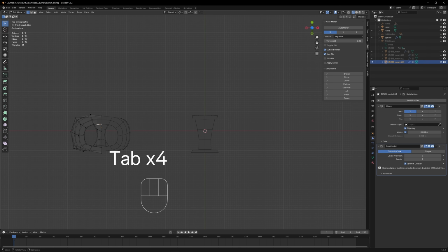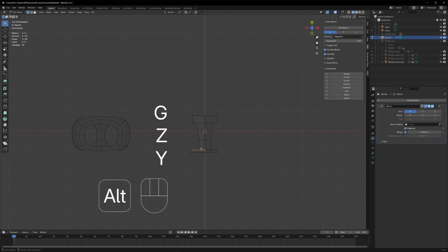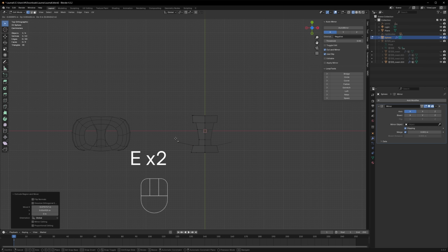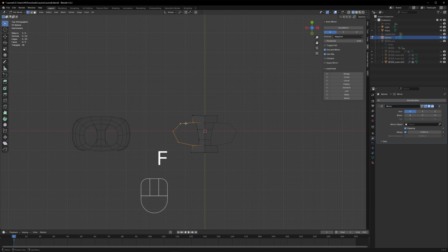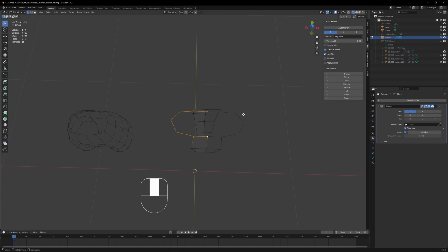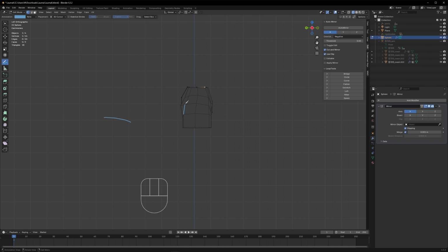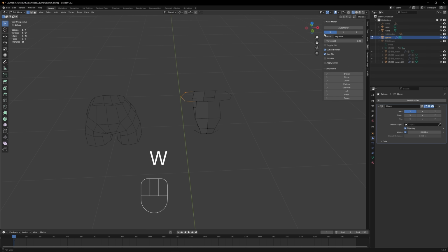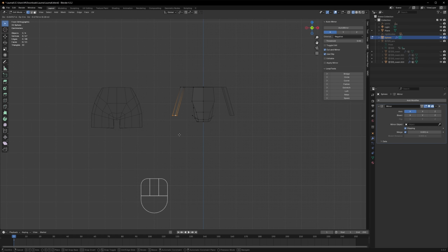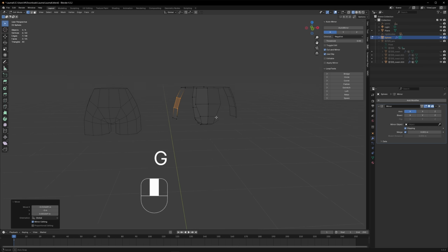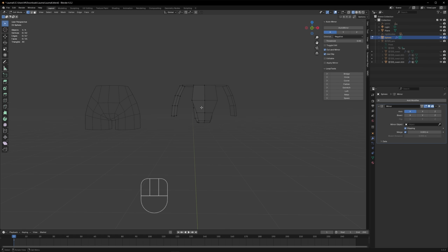Then I look from the top and I see that the top loop is basically an open 2x2. So I just need to extrude out from the top faces a total of 3 new points. Now looking from the top, this part will have 2 edges on the top hand side, left hand side, and bottom side. That's the opening for the torso complete. And now if we look at the side of this object, we'll see another simple shape, a 2x3 rectangle. So by now you know the drill. Extrude that out, loop cut it, and curve it. So that's the entire side of it complete.